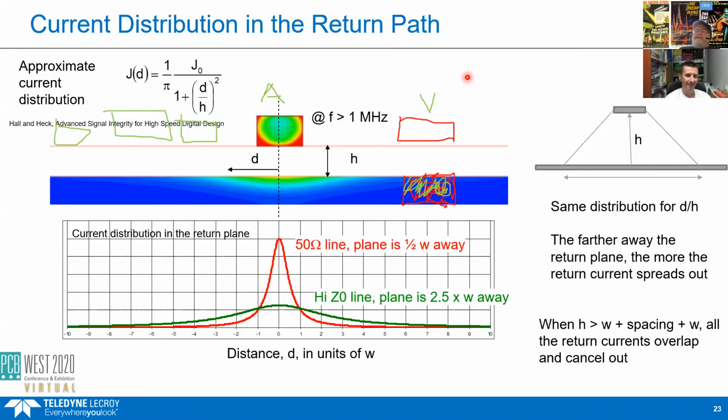And all of these effects that we've been talking about today and previously are the basic fundamental principles of signal integrity. If you really have a good understanding of the principles, you'll be able to determine what direction to go: longer, shorter, farther, closer, thicker, thinner. If you understand the principles, you can tell what direction will reduce that noise. And then armed with the simulation analysis tools, you'll be able to estimate: is it far enough? Is it thick enough? Is it thin enough?